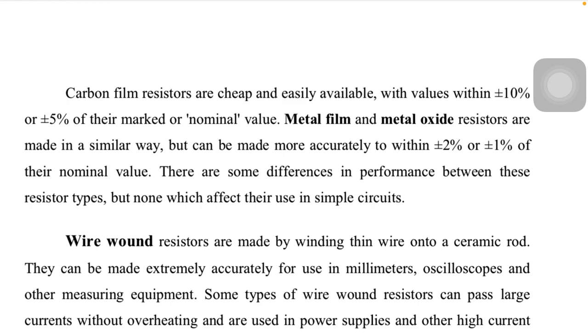So you look for 10% of 10 ohms. So you deduct it, or you add it to the 10 ohms. Okay, I believe if you read through in the previous lesson, you'll get it. So for carbon film, the error is greater, but it's cheaper. For metal film, the error is smaller, but it is more expensive.